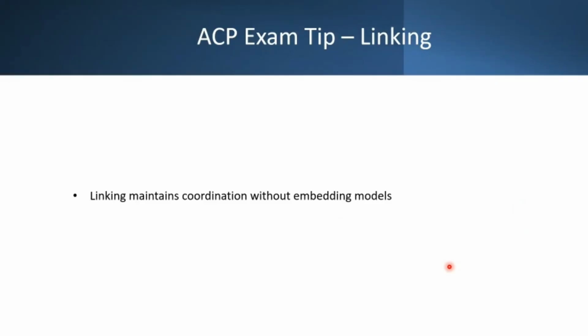The tip for the exam is that you need to learn linking. Linking maintains coordination without embedding the models, and it is the best practice for collaboration and also for using those inputs and files in your project.